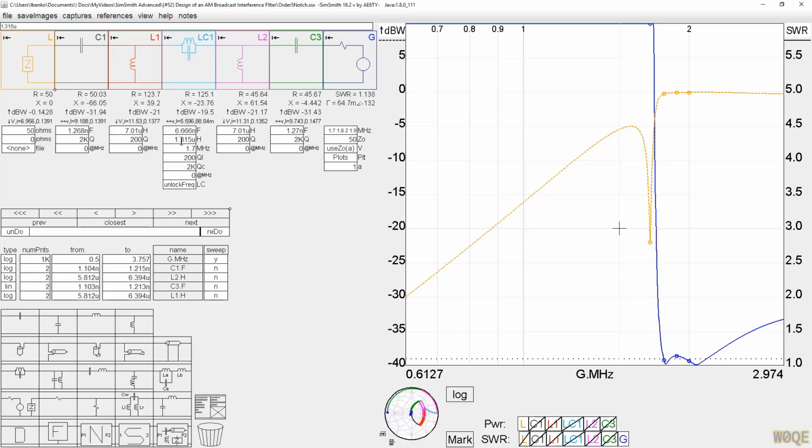So you would need to match this. Although having the frequency matched is important, having the actual components, if I move them in lockstep, 1%, really makes very little difference. So you would need to make sure that this was resonant exactly where you wanted it. But if you live in a place where you need 20 dB of attenuation 100 kilohertz away, beggars can't be choosers here. You can't be quite as picky. You could actually transmit through this filter too, just fine. And if you actually had a station that was that close to you, you might want to transmit through it.